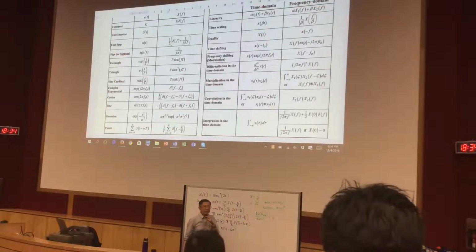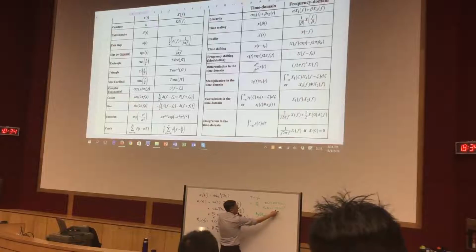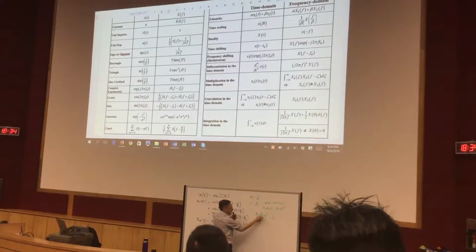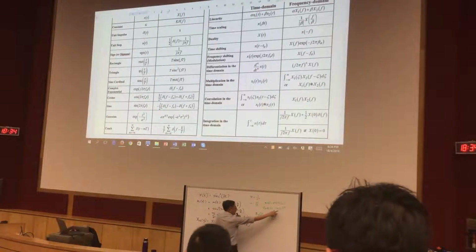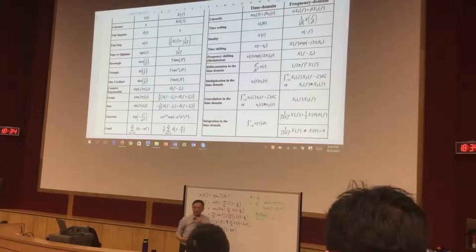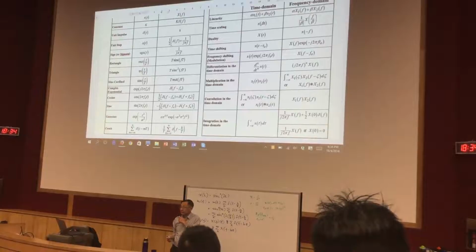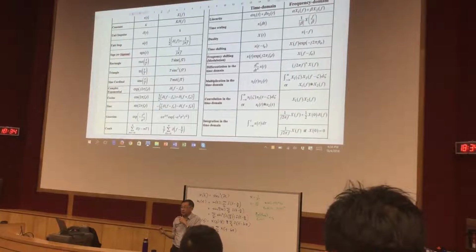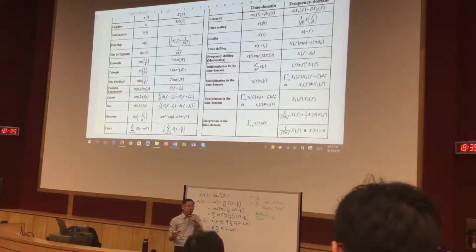That's 3 dB bandwidth. So you already found the formula for this. Change f to f3 dB. This is known when this is 0. It's a number. Substitute, the only unknown is f3 dB. Solve for f3 dB. Okay?